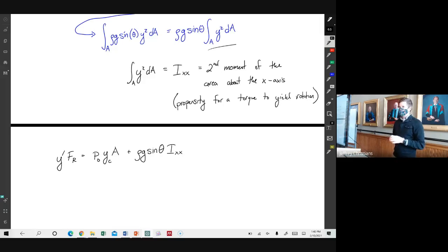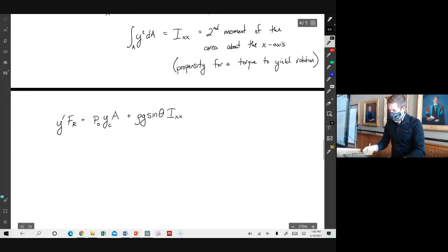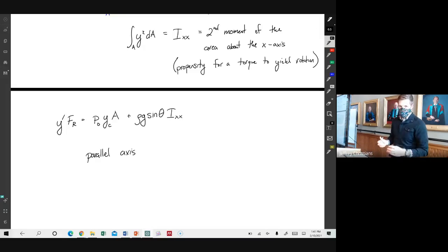But we look it up, so you might be interested in the rotation about, say, a hinge at the shape's edge. What people have probably calculated before is the propensity of that shape to rotate about the center. So you have to figure out how we relate something rotating about the center to rotating about one edge. How are those two things related? So we use what's called the parallel axis theorem. We're not going to do anything more with that other than what we'll do right here.